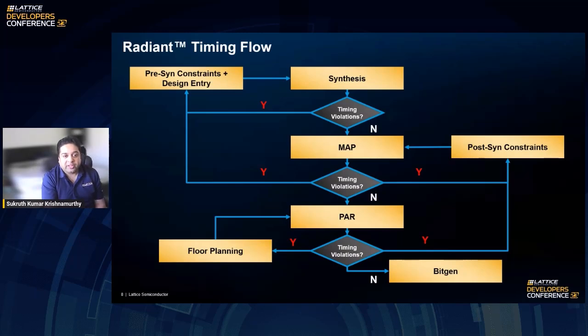At this stage, if you see a large routing delay, then probably running par might fix those issues because this is still an estimated timing. Once you see no timing violations, run par on the design. Once you run par, run that final timing analysis. In this stage, if you see timing violations, and if the failing path has a large logic delay, then this has to do with the RTL. If it is not the logical delay and if it is a routing delay, look at the timing constraints provided. In certain cases, users might also have to do floor planning to reach timing and close timing of this design. Once you close timing, run bitgen and validate the design on the hardware.